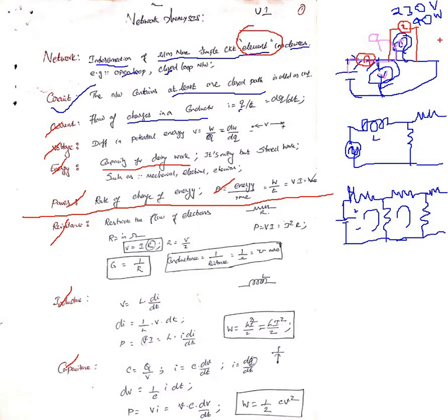The multimeter will show around 200 ohm, or 150 ohm, across the lamp. What does it mean? It shows that the lamp has resistance. If the resistance value is less, the flow of current is more, and the brightness is better. If the resistance value increases, the flow of current is minimized. You reduce the flow of current.